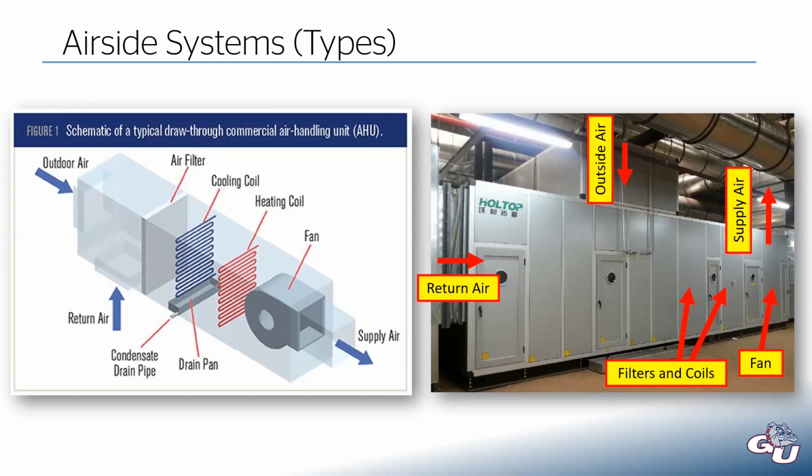One thing that's not shown in either of these diagrams, that just came to mind, is the relief. So recall, if we're bringing in outside air, we have to relieve the stale air in equal amounts, or else the building becomes pressurized. Sometimes that's built into the unit, but sometimes that relief happens somewhere else in the building. And that's probably what's happening in this case.